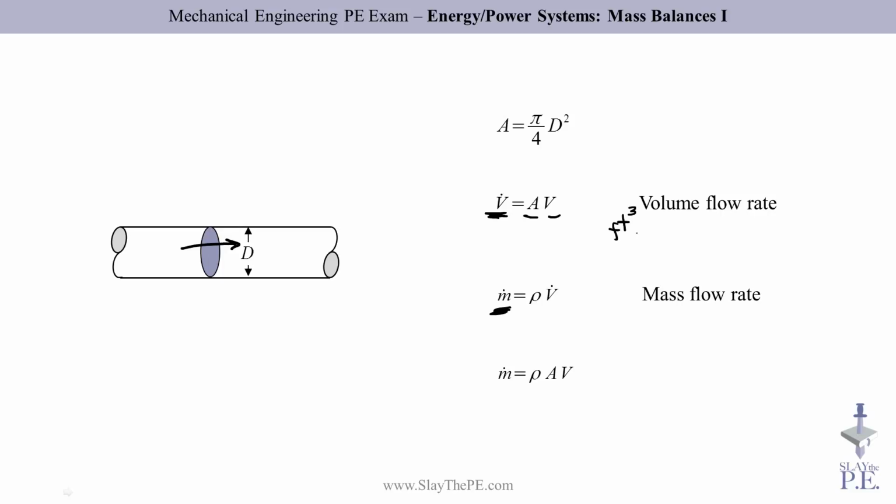So you'd see something like cubic feet per hour, or liter per second, or gallon per minute, or cubic meter per hour, or the CFM, cubic feet per minute. That's a unit that the HVAC folks should be quite familiar with. Also, depending on the field, you might be familiar with something like barrels per day, etc. So the point is that that's volume per unit time.